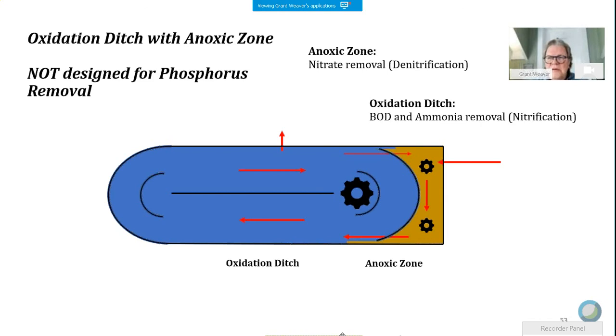Okay, so that there's just enough oxygen in the bottom going from right to left to support ammonia removal, and most of the oxygen is depleted and sufficiently depleted so that by the time it goes to the right, the top moving left to right, there's so little oxygen left that it will go anoxic, and therefore the bacteria, to stay alive and to grow as they go through that zone, are going to breathe the nitrates off.